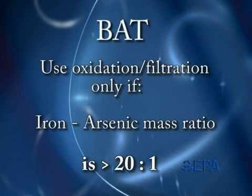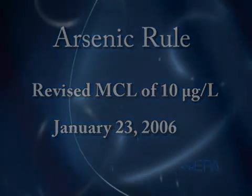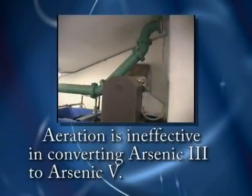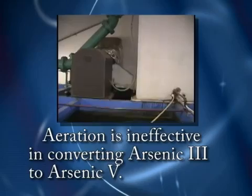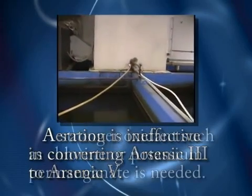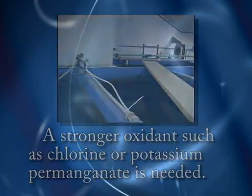EPA determined that they would list oxidation filtration as a BAT only under the condition that the iron to arsenic mass ratio was greater than 20:1. This treatment method can be used to meet the revised MCL of 10 micrograms per liter. The practice of aeration for iron oxidation has been shown to be ineffective to convert arsenic-3 to arsenic-5. A stronger oxidant such as chlorine or potassium permanganate is needed.